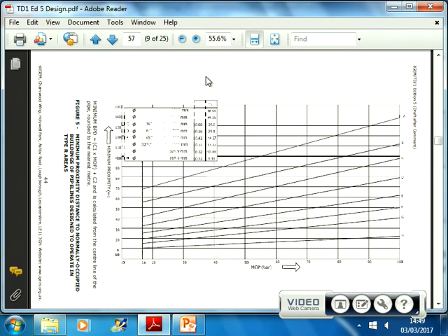So you know that the pipeline has been operating at 75 bar. You know what its diameter is, so you can calculate what its current proximity distance is. Then you need to calculate what a proximity distance would be when you've changed its use to CO2. And you're going to have to go to the 8010 code to calculate that.